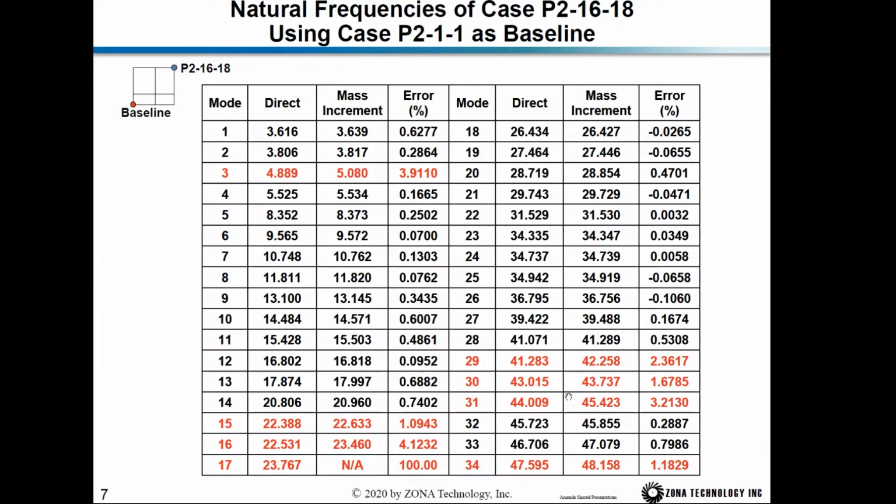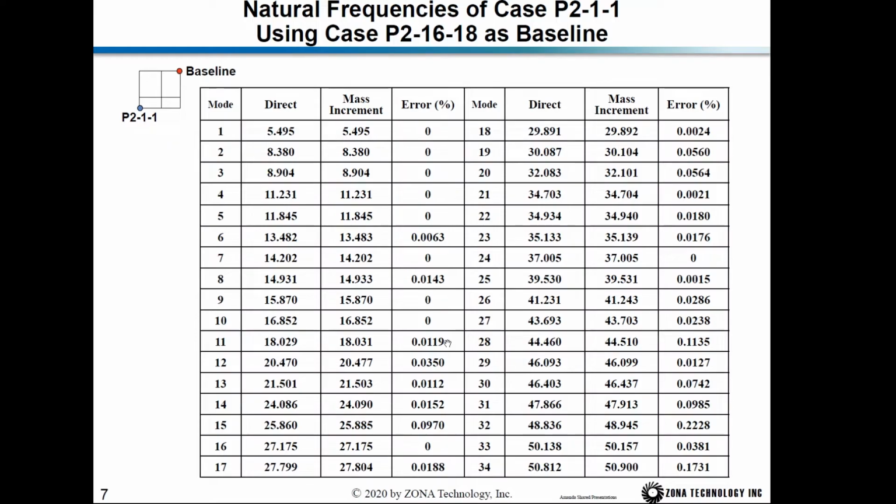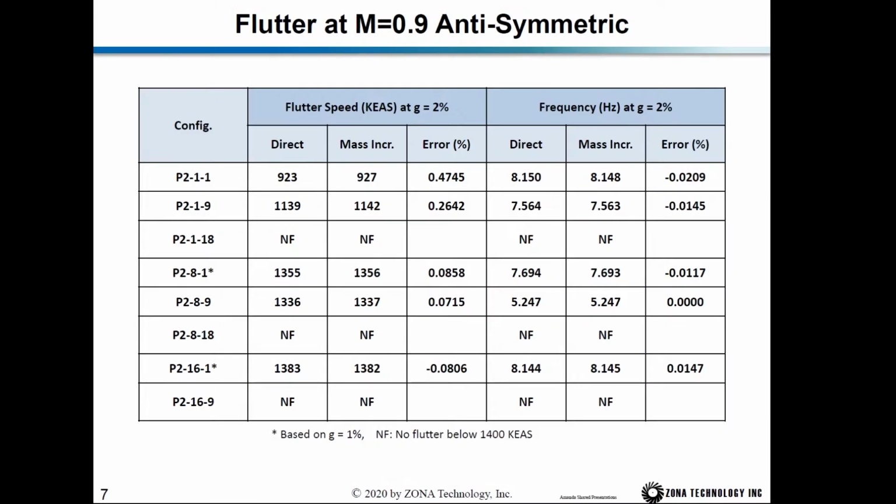This proves that if we want to perform the flutter analysis, you have to use the fully loaded store configuration as the baseline mode and include a lot of modes. Then in the flutter analysis, you take out some modes.